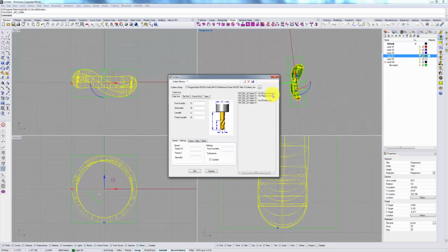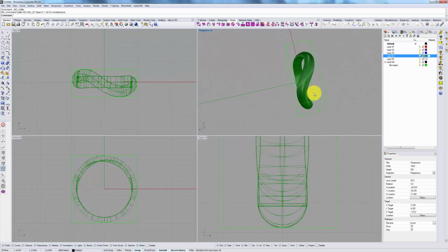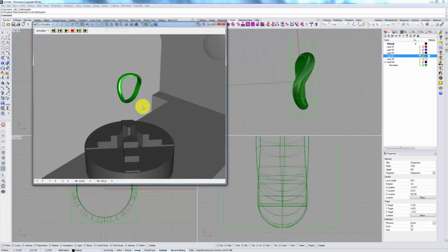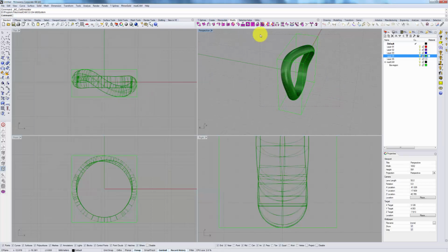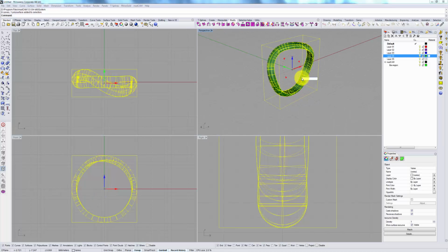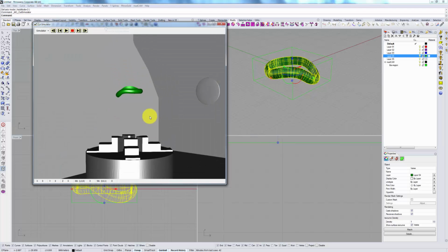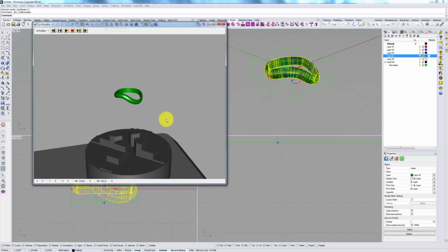So as you may recall, I suggested that for 5-axis simultaneous we pick a higher feed speed if your controller is something like Mach 3 rather, and has issues with its feeds for simultaneous operations. And let's make sure we position it correctly. So this is not the correct way to position it. So let's rotate it by 90 degrees, reselect it, and make sure now we're in parallel with our chuck and the axis. So this is looking good.